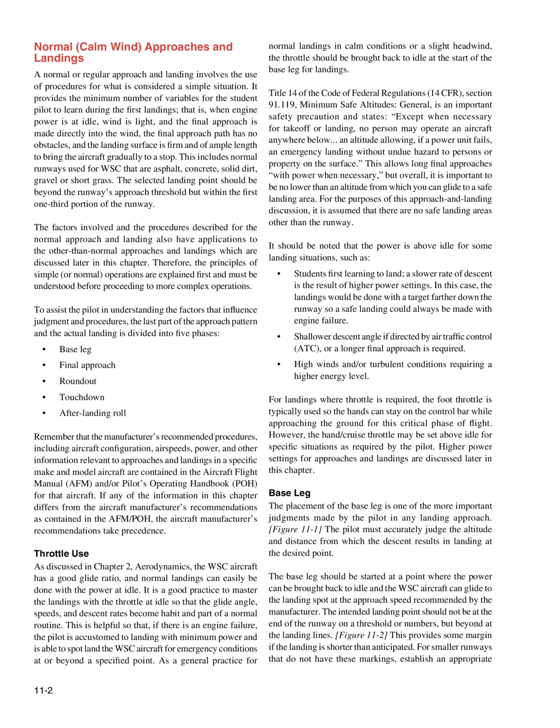Base leg. The placement of the base leg is one of the more important judgments made by the pilot in any landing approach. Figure 11.1. The pilot must accurately judge the altitude and distance from which the descent results in landing at the desired point.